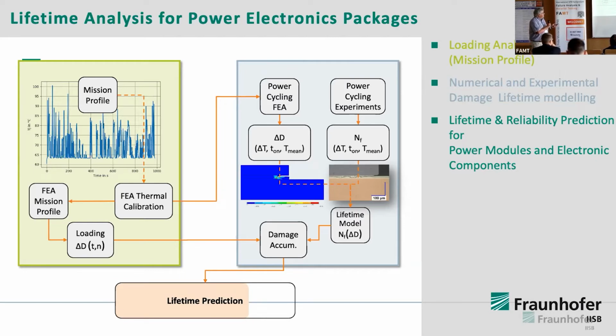And then sooner or later, a crack, for example, chip on a substrate, and the solder layer will generate a crack. And with the crack propagating, the device will fail because the temperature is getting higher and higher and higher. And with this, you can do an empirical lifetime model like most of the industry does. You calculate an accumulated damage, and you can say, okay, my lifetime is more or less eaten up to 80%, and I have 20% very likely lifetime of the device.